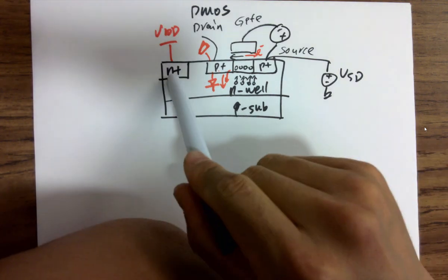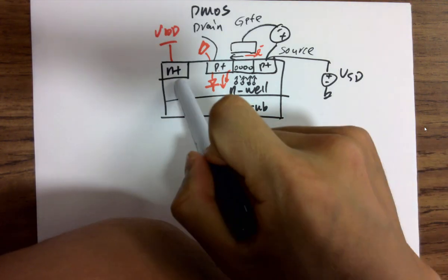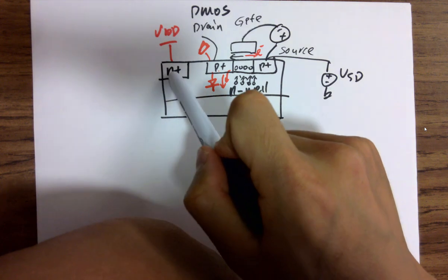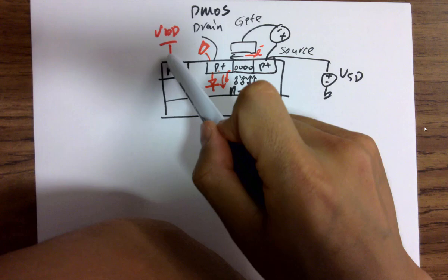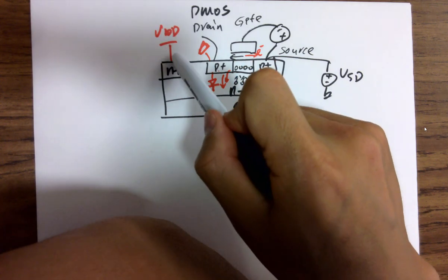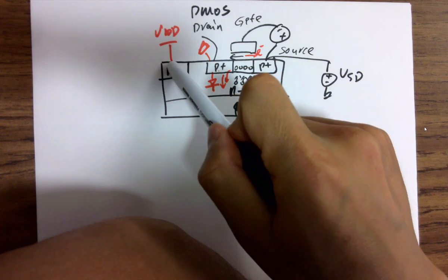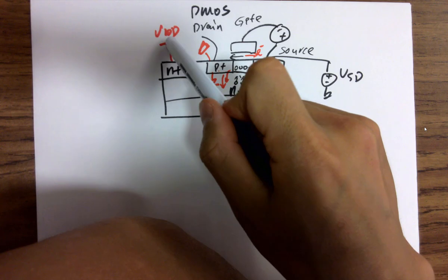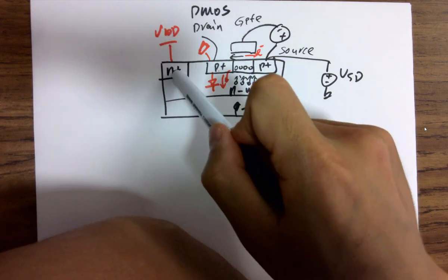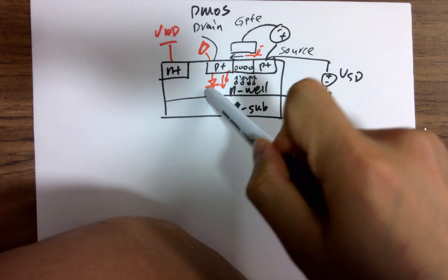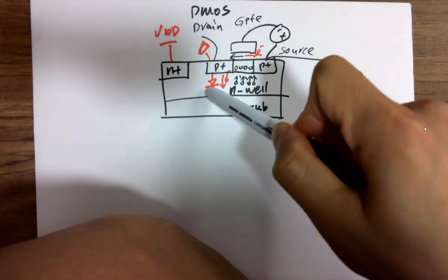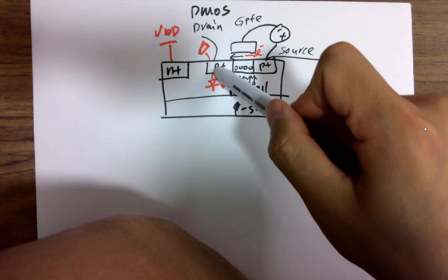The N well tap, which is N+, heavily doped N-type material, is directly implanted into the N well, making a good connection. Then we use vias and eventually get a metal on top of the heavily doped N+ node, and we short this node to VDD. So the cathode of the diode always has a higher potential, so you never forward bias the diode.